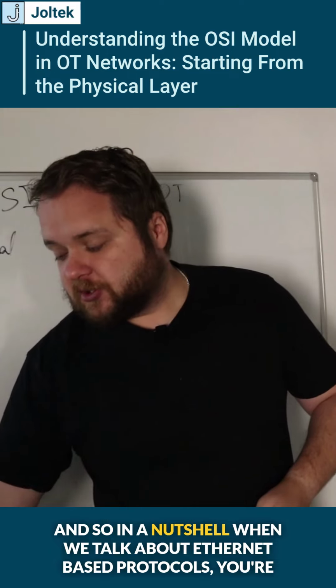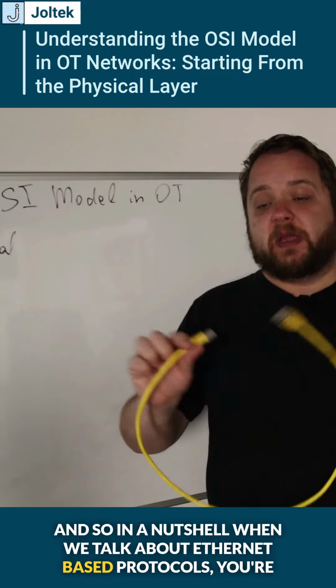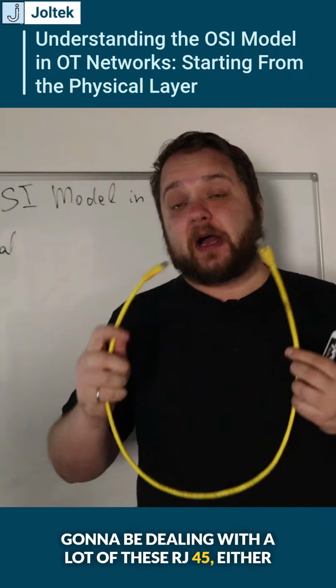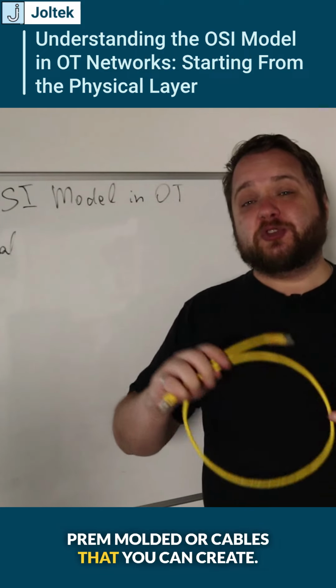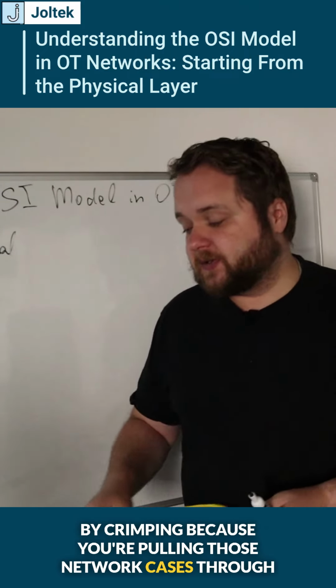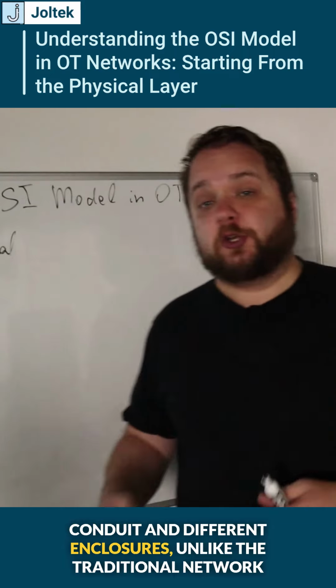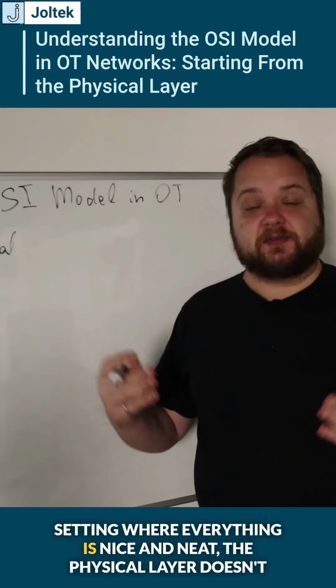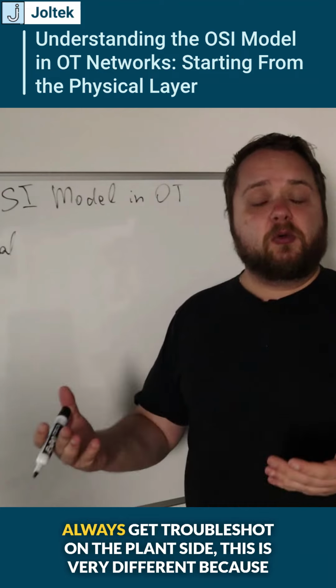And so in a nutshell, when we talk about Ethernet-based protocols, you're going to be dealing with a lot of these RJ45 connectors, either pre-molded or cables that you can create by crimping, because you're pulling those network cables through conduit and different enclosures. Unlike the traditional network setting where everything is nice and neat, the physical layer doesn't always get